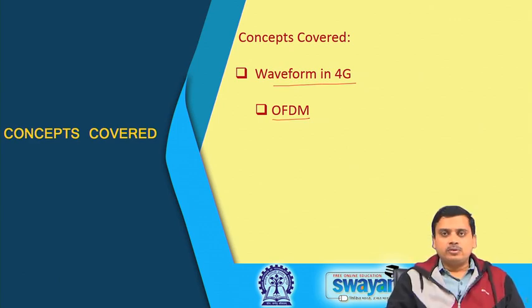So, we had also discussed how the M-ary FSK could be designed in a manner that the frequencies that are being chosen for operation are orthogonal in nature, and we had also said that since they are orthogonal, it is possible that you not only use them for switching between the carriers and letting information flow by virtue of choice of a carrier, you can actually use all the carriers simultaneously, and that would appear as FDM.